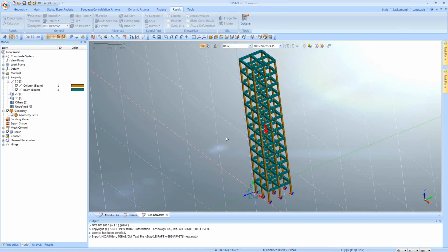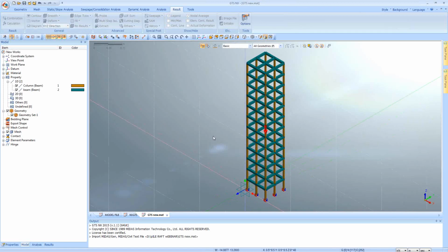Now here it is only 9 columns, but when you have n number of columns, you want to make sure that where you get the nodes, you get the nodes at the column location. So what we'll do is that we'll now create the soil model around it. First of all, let us delete the supports. So you can see this is model.